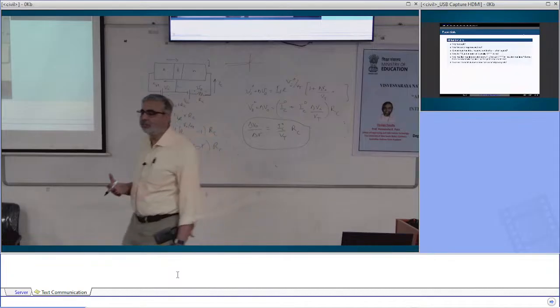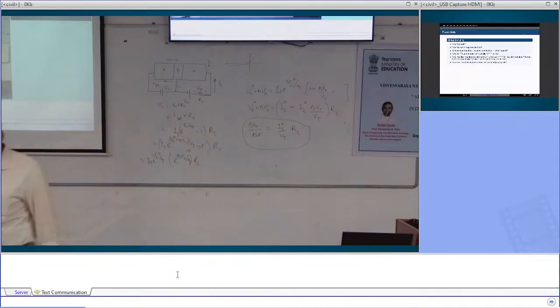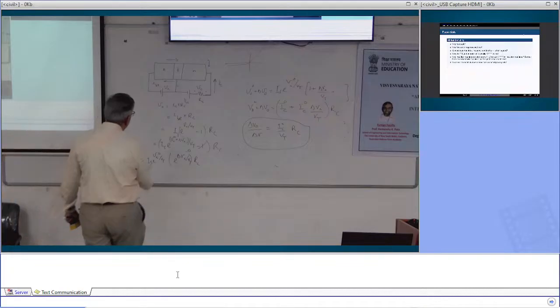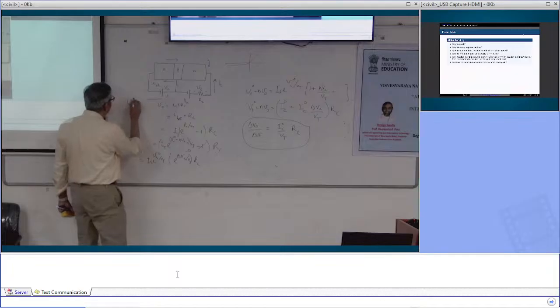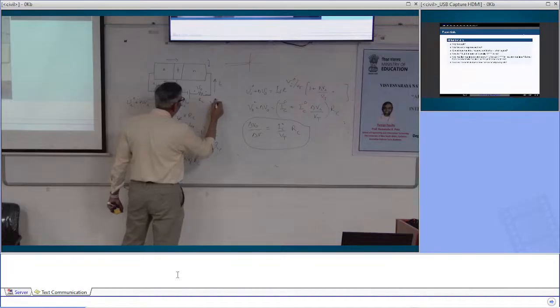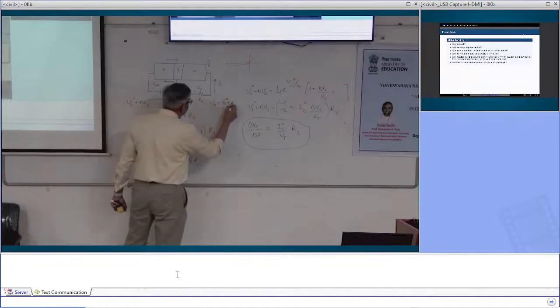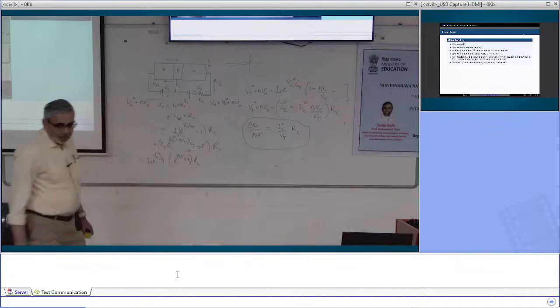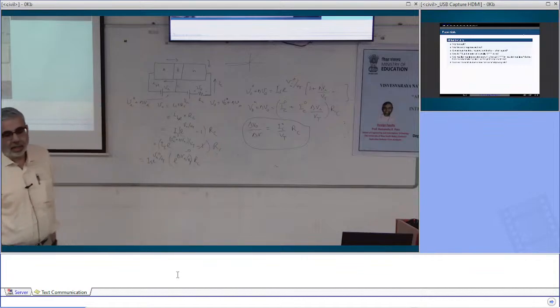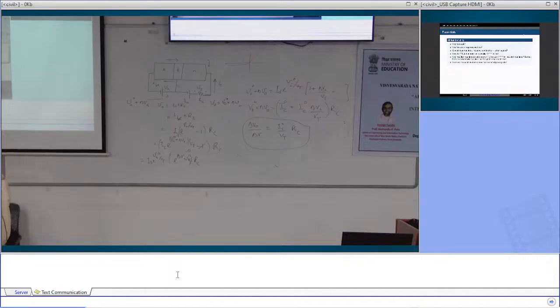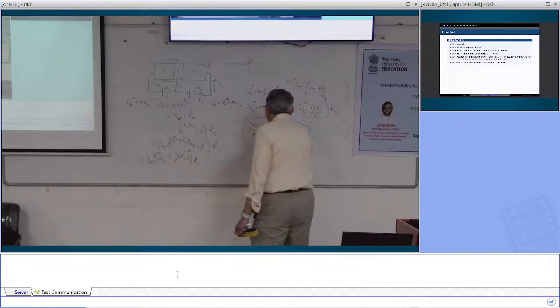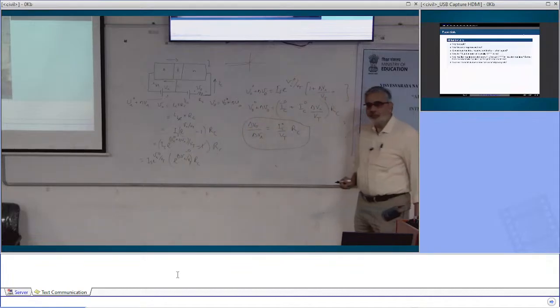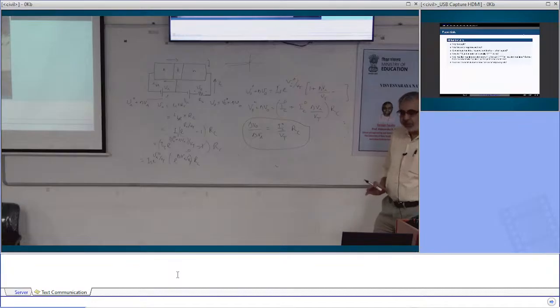So IC0 is the bias current. I didn't want to get into that, but there is no option. So that is the current due to the voltage VI0. So this voltage is VI0 plus delta VI. This voltage Vout is Vout0 plus delta Vout. Okay, so I'm getting the change in the output voltage due to the change in the input voltage. And that's the expression I get.